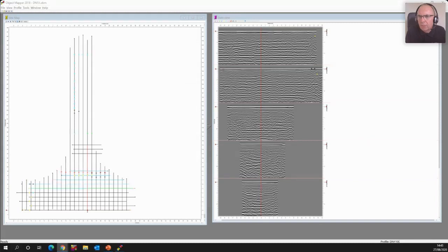What else do we get? We had a question on different velocities in one radargram from Kate. But I think that you meant that we can have different velocities for different radargrams and not in the same radargram. Yeah, exactly. When we insert the hyperbola fit or set the velocity, it will be for the whole of that one profile. I can't change it in the horizontal.